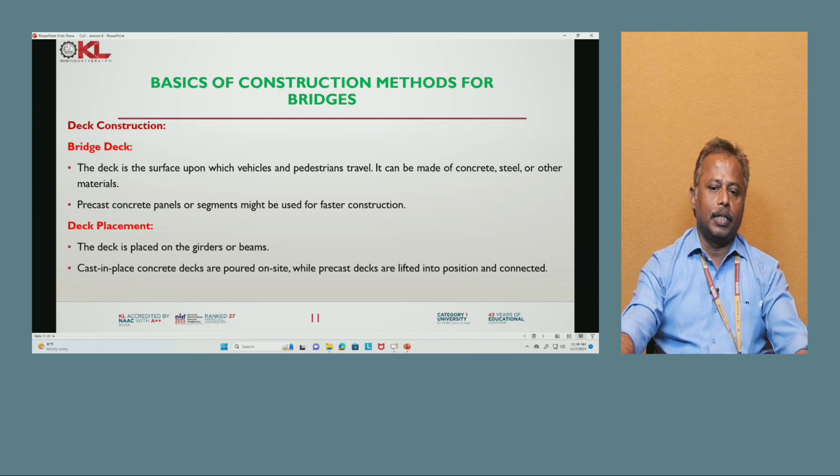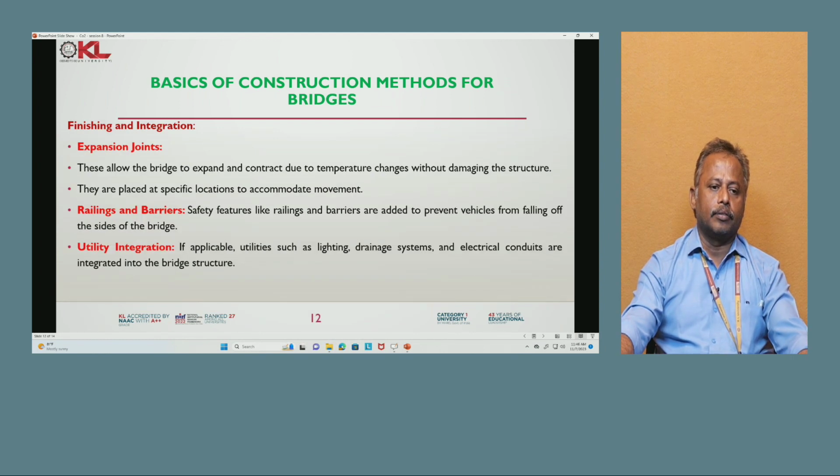Next, deck placement. The deck is placed on the girder or beam. The cast-in-place concrete decks are poured on site, while precast decks are lifted to the position and connected.